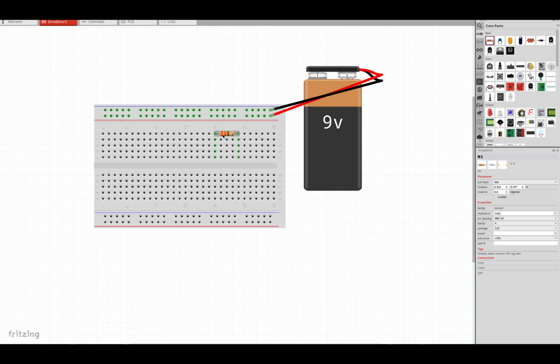And notice how the color bands change over here, right? You see this becomes orange, this is brown, so this is 3, and the multiplier is 10 ohm, so we get 330 ohm. And let's not care about the tolerance band over here.